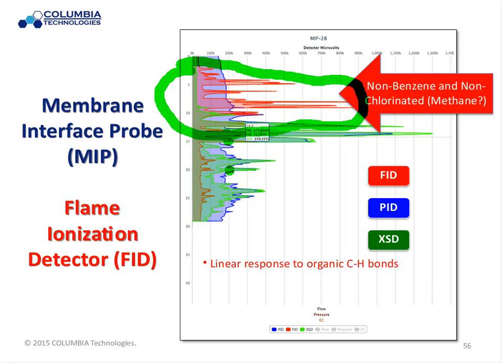So most likely we've got a groundwater level right here at around 10 meters or so, maybe even shallower, and what we've got is evidence of microbial activity above the groundwater. That's essentially our vapor intrusion question, if you want. It's not a double bonded benzene compound, and it's not a chlorinated compound, so we're most likely looking at methanogenesis. So it's an example of how you can look at groups of compounds off the detector suite.